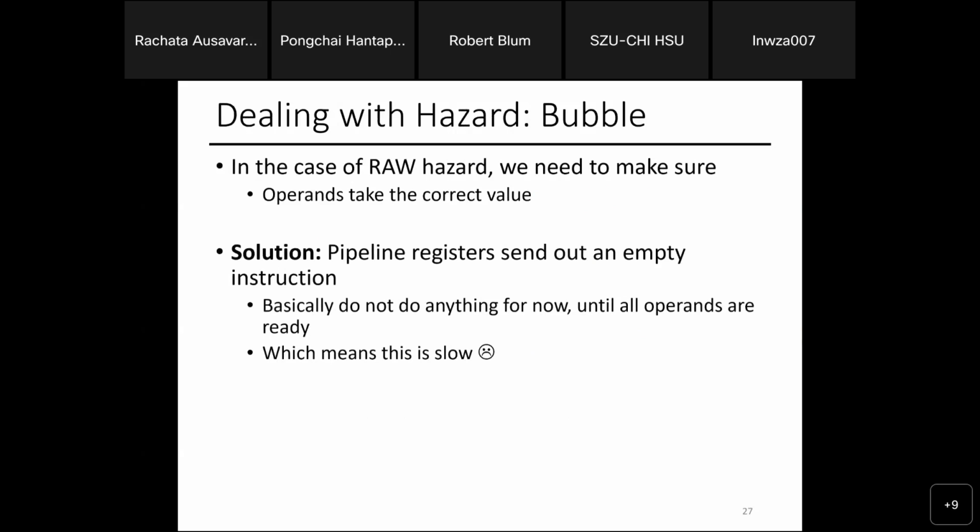I know that, let's say I need R0, and I know that I have to wait until R0 is in the register file, right? But is the value of R0 somewhere in my design? I mean, in theory, it's the output of my adder, right? If I can sneakily take the signal from the output of my ALU and plug it in as an input, I'm done. We call this data forwarding. Again, every single CPU does this.